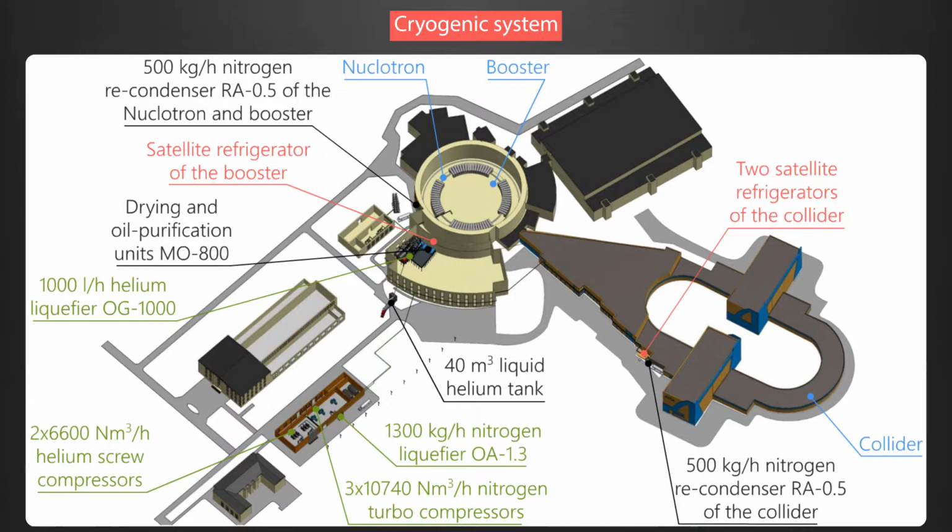Besides that, additional voltage appears as a result of the magnetic reversal of the magnets, due to the whirling currents in the coils. Additional voltage may occur if one of the coils accidentally changes into a normal conducting phase, while there is active resistance on this coil. This extra voltage on a magnet needs to be detected by the quench detection system. The voltage has a value at the level of hundreds of volts of inductive voltage.